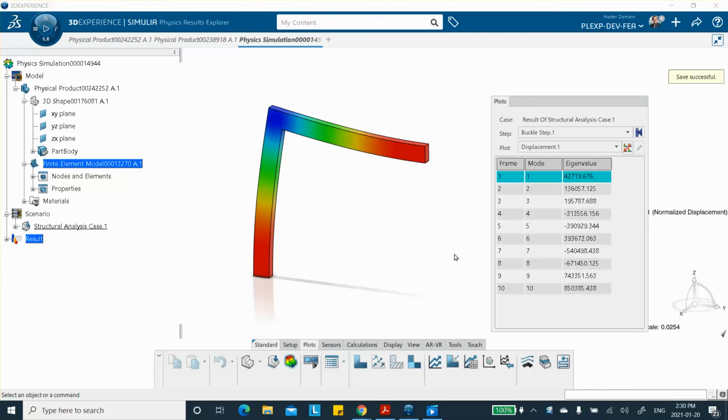Oh, there's something that I forgot to tell you, and that is actually the buckling load is going to be double of this because we modeled only half of this structure. Remember, we cut it into half. So you really have to multiply this thing by 2. So the 1 pound dummy force times this eigenvalue times 2 is going to give you the actual compressive buckling load that you're going to apply there.